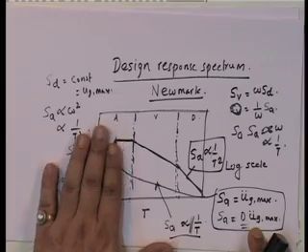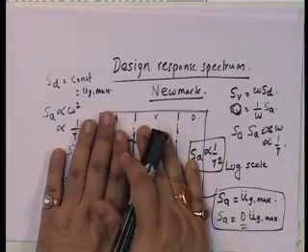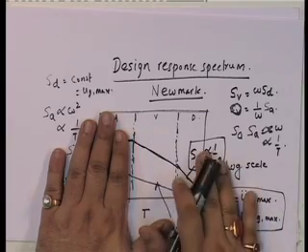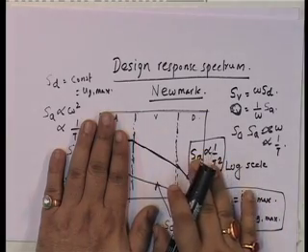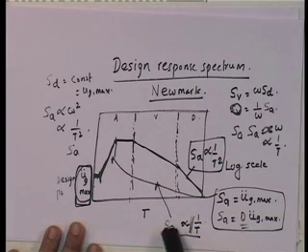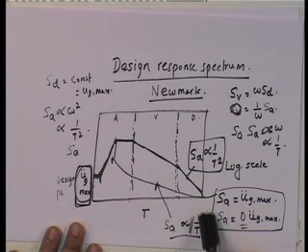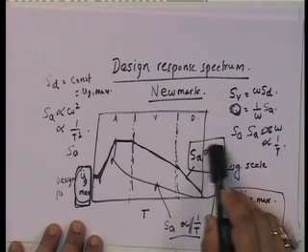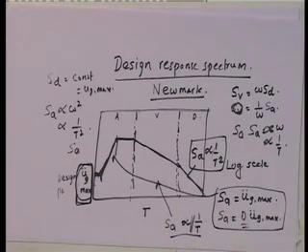Okay. So, therefore, there is a transition zone, but in the velocity controlled zone S v remains a constant, and in the displacement controlled zone S d remains a constant. So, automatically S A is equal to some constant times 1 upon t, and S A equal to some constant times 1 upon t squared, and this in essence is your design spectrum.